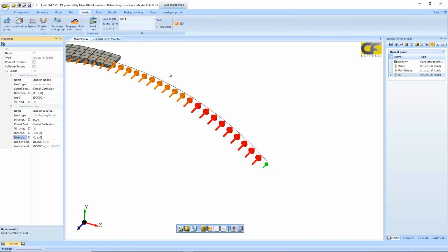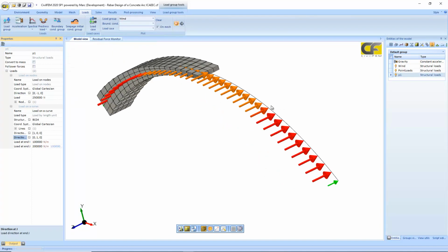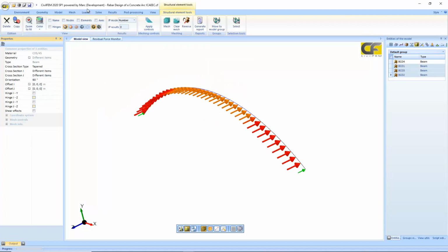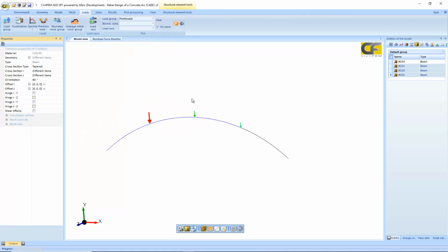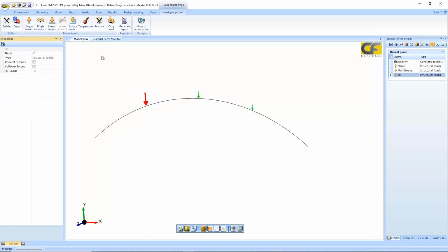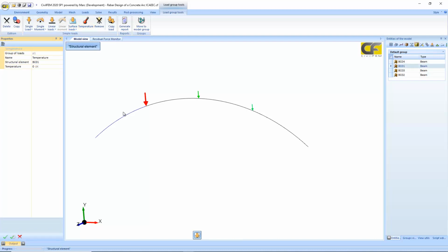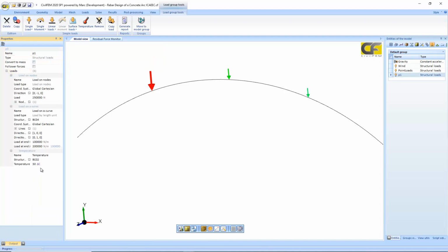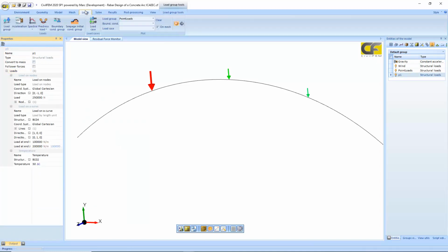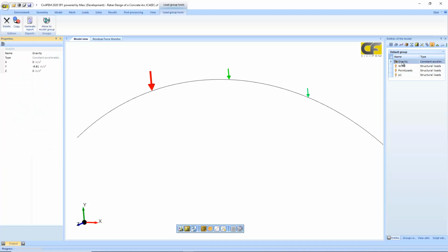Here there was a wind pressure following the set direction, applied here, along with forces which are 3 point loads. You can see that in the statement of the exercise. There are other types of forces: temperature forces and surface loads as well, but we don't have surfaces here. To apply a temperature, just select the structural element it applies to and the temperature increase in the different units. A gradient of 30 degrees on the full structural element. We have other types of forces, such as setting an acceleration, same as gravity, which is always defined automatically by default.